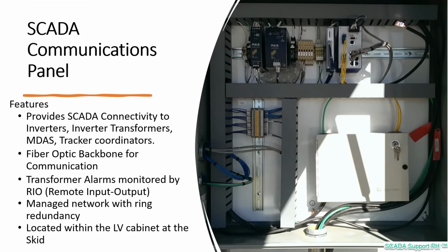On a PV power plant, data communication and monitoring on the skid level is very important. And this is where your SCADA Communications Panel comes in. This provides SCADA connectivity to your inverters, inverter transformers, MDAS, and tracker coordinators.